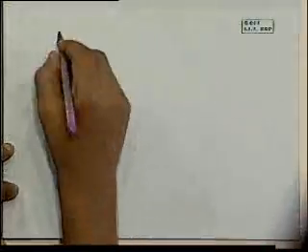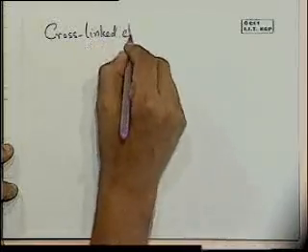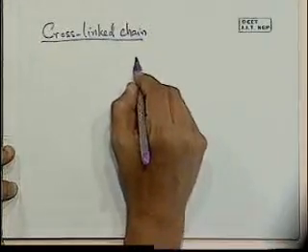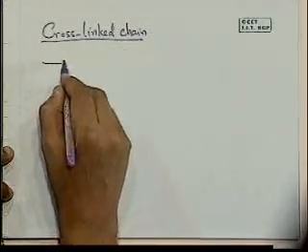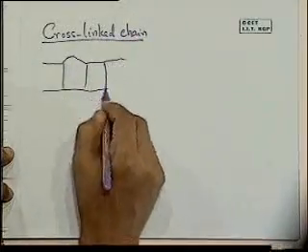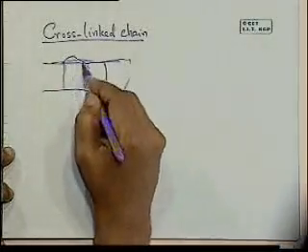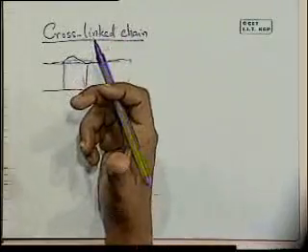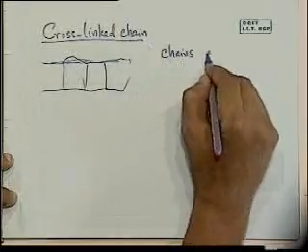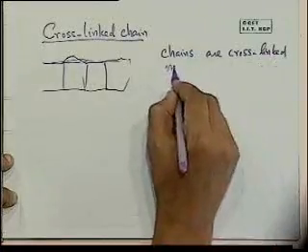You've got another category, what are known as the cross-linked chain. Here also we've got long chains, but they are cross-linked properly. So we've again got longer chains, except there's good linking between these chains. They are not weak bonds there, they are fairly strongly bonded between the chains by these cross-links. The chains are cross-linked and therefore cannot move easily. So we've got more rigidity.